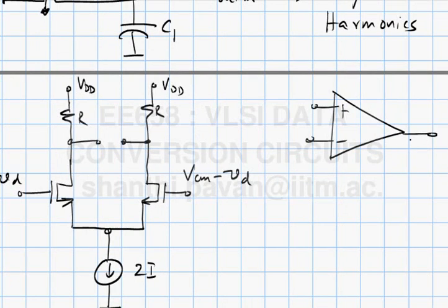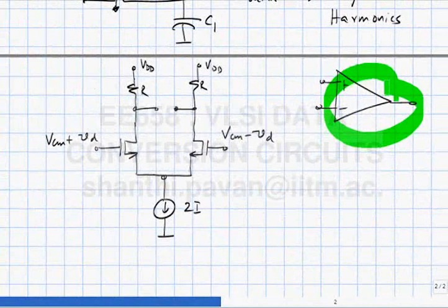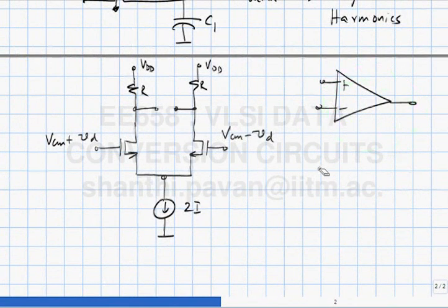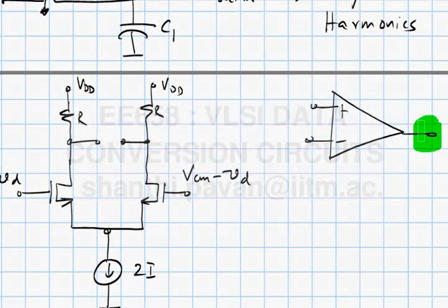you can't have an output voltage floating, right? A potential is always a potential difference. It's between two nodes. In an op amp like this, where is the other node for the output? It is understood to be ground. So this is what is called a single-ended op amp. In other words, the input is the difference between the two, but the output is referred to ground. So this absolute value is what you look at.